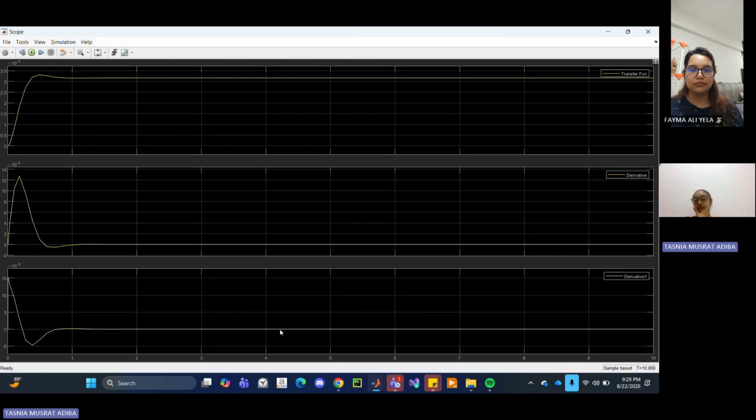So the damping coefficient is 0.7, which is industry standard for second order vibration systems, which this is a second order vibration system. And the overshoot for my results is only 4.6%. So it becomes steady very soon, as you can see from the displacement curve. Since the overshoot is pretty low, the steadiness is quick without excessive displacement.